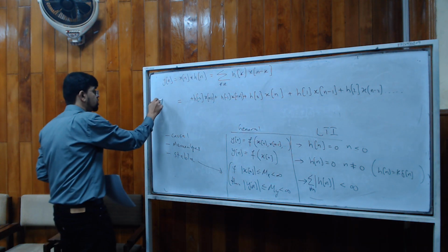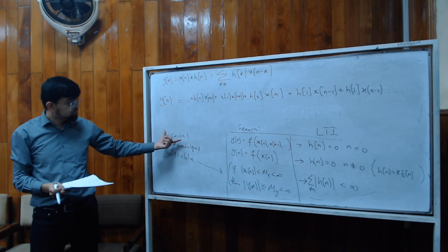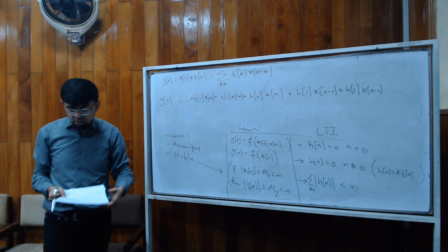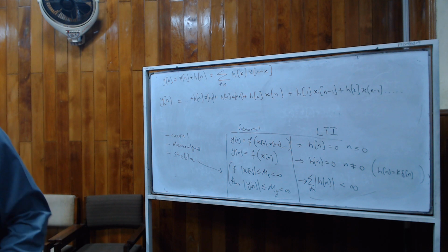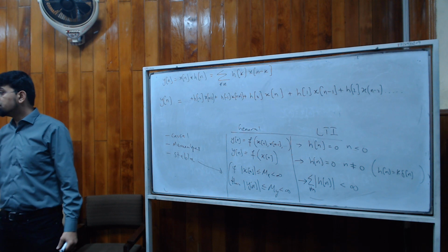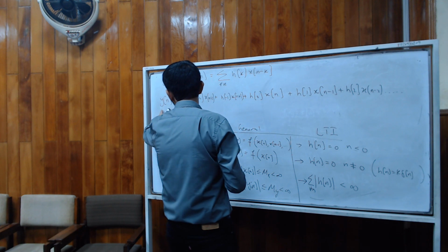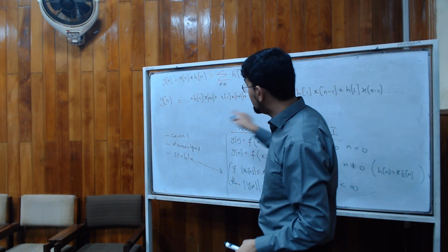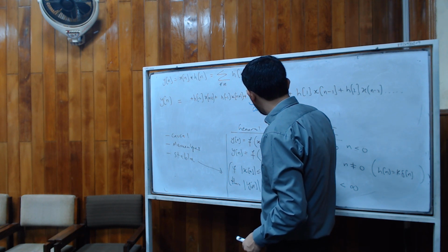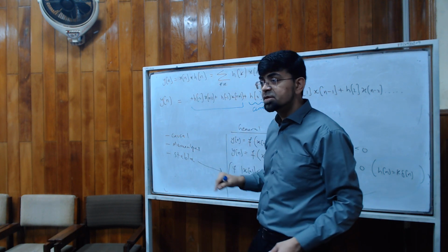Now this is the output. Let's apply the general definitions of causality, memoryless, and stability on this output now. Firstly, notice which term represents the current input. If it is y[n], say y[3], then x[3], so x[n] is the current input. What about these, x[n+2], x[n+1]?